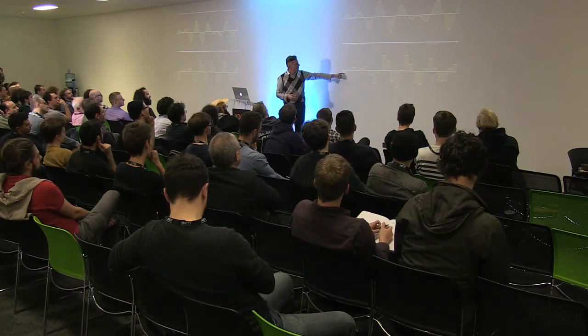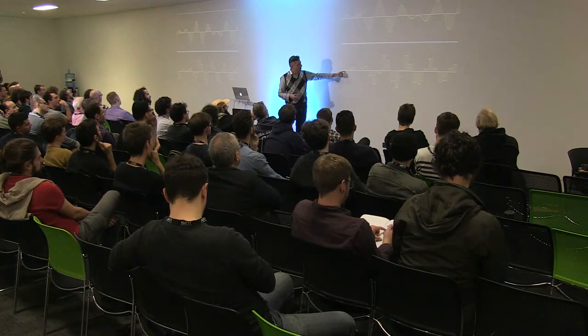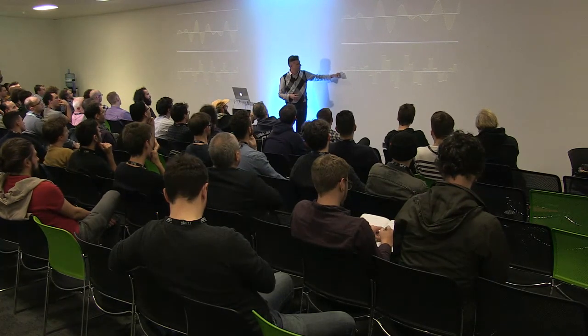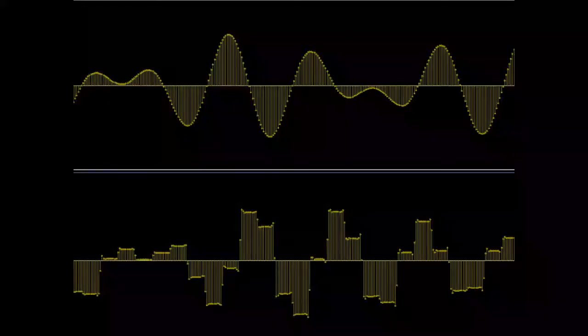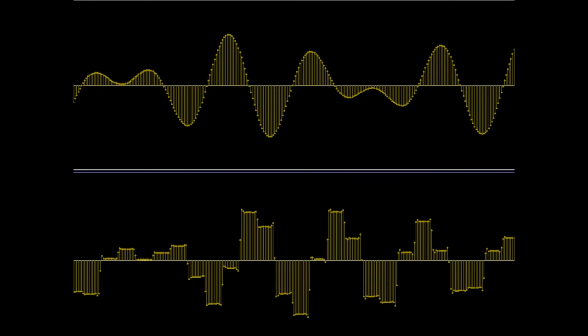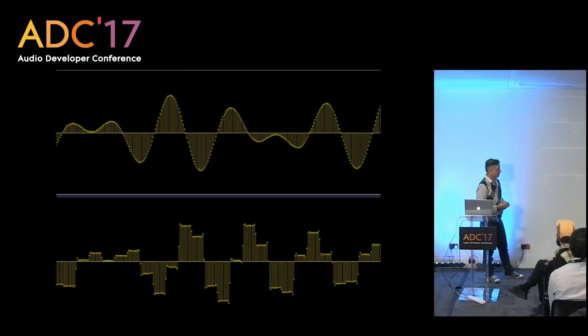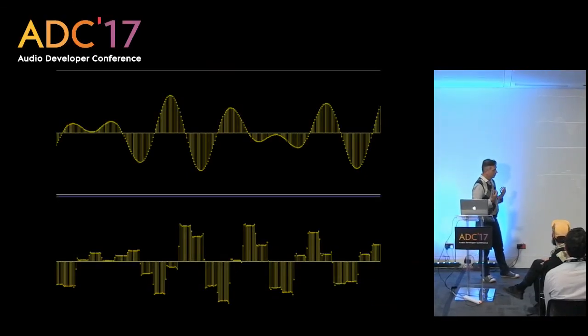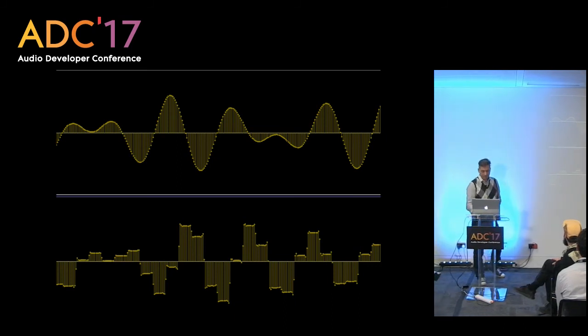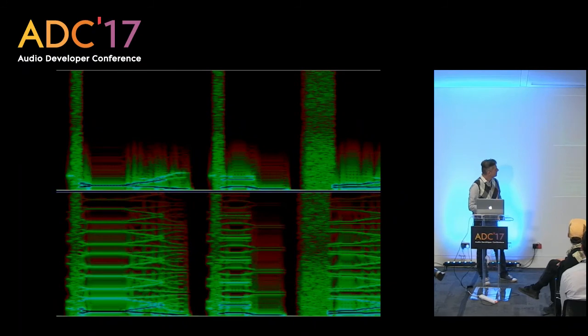And this is kind of the output using the BLIP for sample rate conversion. It's not sample and hold. You can see that it's not just DC plateaus, but the exact time where the transition happens is a little bit below 8 kilohertz. And if you implement it, you can even modulate that in real time, get some very nice effects.